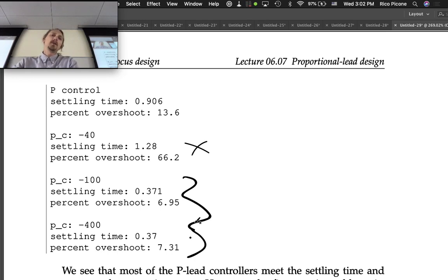And think about this too. This is just a general design consideration, but if you're designing a controller, hopefully you have your factor of safety built into this, right? So you say, okay, I want my settling time to be 0.4 seconds because, if it was 1 second, or 1,200 milliseconds, or 3, 4, 5 times what this is, then it would be dangerous, right? So you want to be designing it with that factor of safety built in.